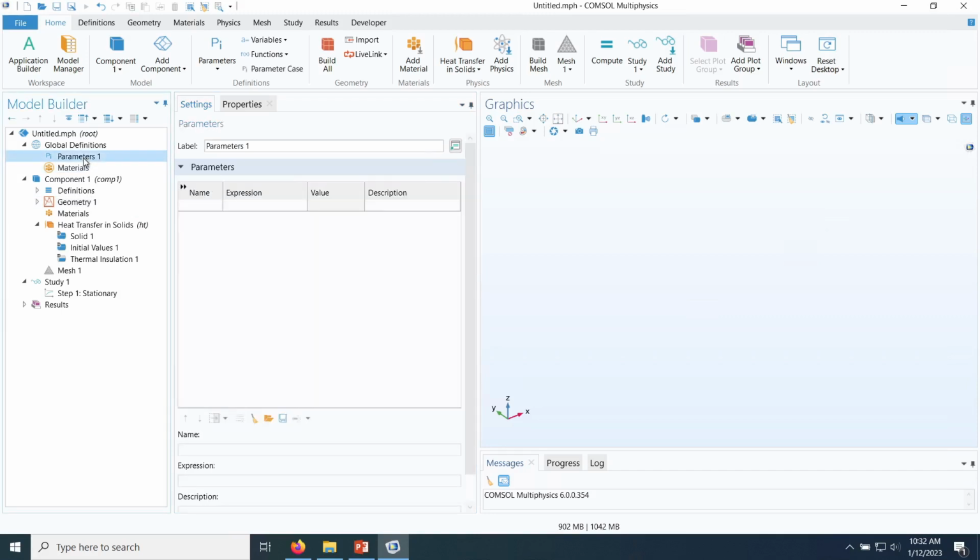So click on the parameters. Again, this is an optional step. You don't need to define parameters. You can just put numbers in the design or geometry part. But if you're doing optimization problems, if you want to change variables that are related to each other in terms of equations or something, defining parameters will make life a lot easier. In this case, I won't be needing to define or relate equations or variables, but I'm going to do parameters